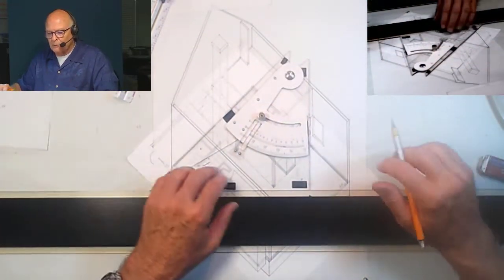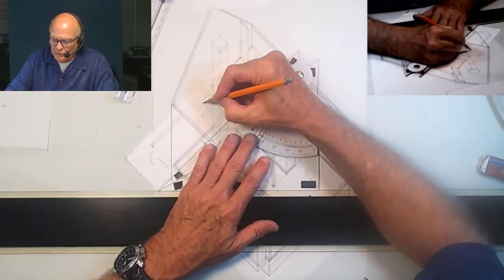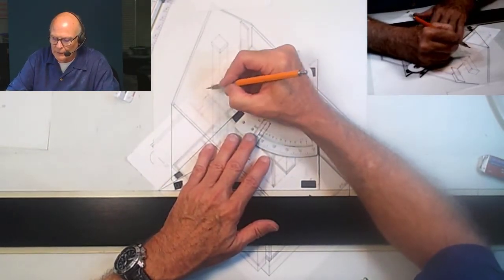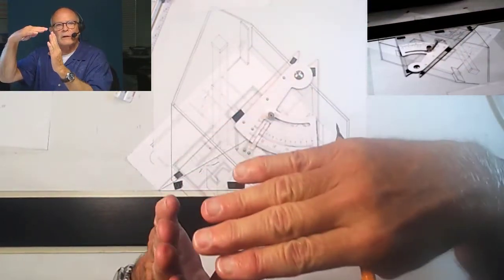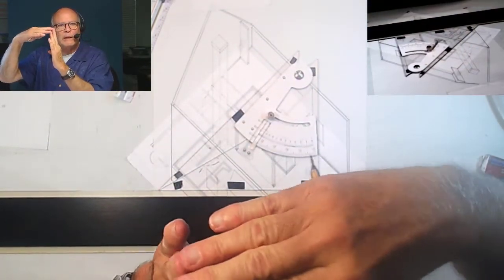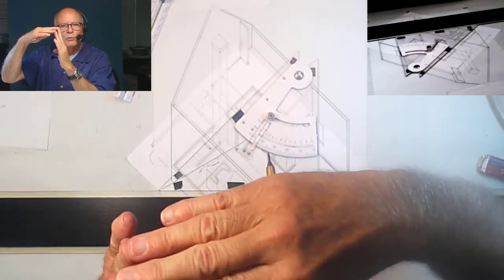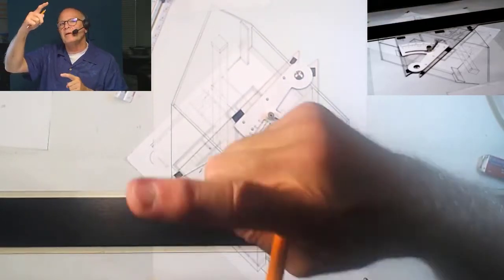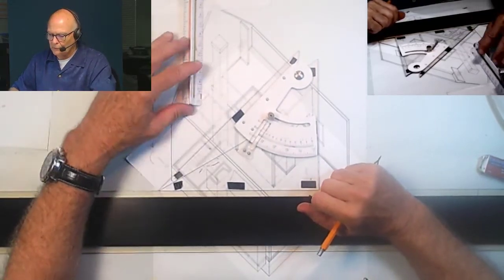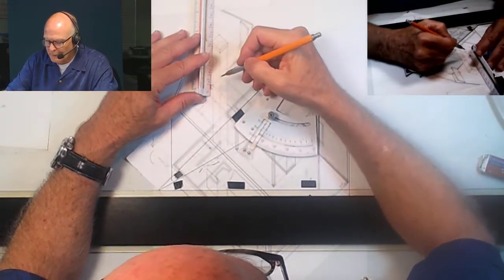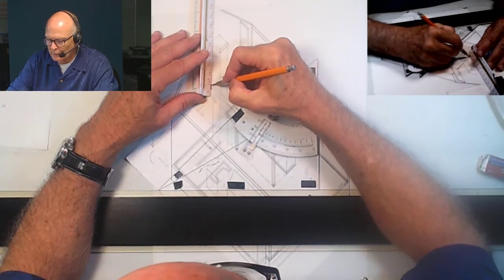Okay, I'm not going to do any more. What I wanted you to see is that, just like last week, the nosing of each of those points, that's where the stair riser meets the stair tread. That nose of the stair, we need to be 42 inches above that in order to make that work. So we measure from here.